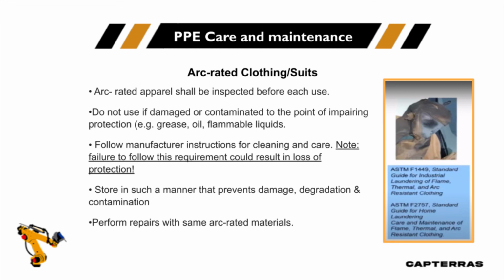If we allow folks to take garments home, it's absolutely essential we have a clear, clean, written laundry program that they're going to follow as a guide, and that they understand it and follow it. I can't tell you how many sites where, even after they've been trained, they forget after a while, and then they're laundering the treatment out. So that's why, again, I look in many cases towards the inherently arc-rated garments as a personal preference, just because of that.